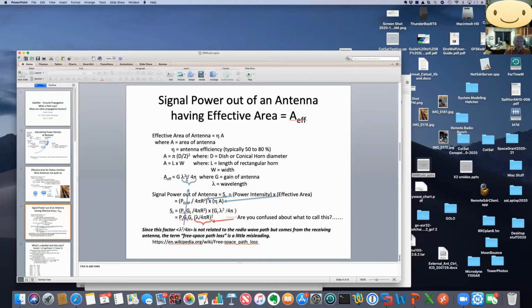Well, I'll give you an example out of my head. We're using a 6-meter dish that runs at a wavelength of 3 centimeters. And so you plug in, you change the parameters around to solve for gain, and it turns out that's about 50 decibels. That's a really big number, 10 to the fifth.